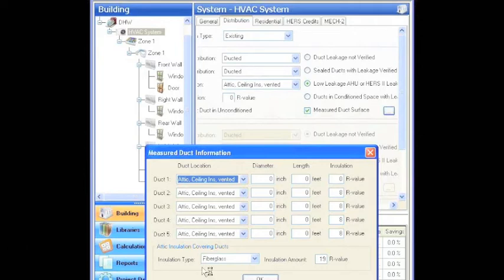And that is where you would want to get into this if you are, say, redesigning the duct system and you are insulating the duct work especially, and or you are doing some deep buried ducts and you want to be able to get credit for that. You will want to go in here and put in the values for the duct work and for the insulation you're putting on top. Because this is assuming you've got covered ducts, that's where this number will be pulled in.